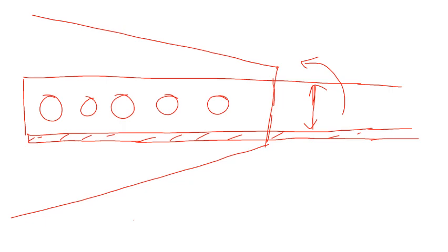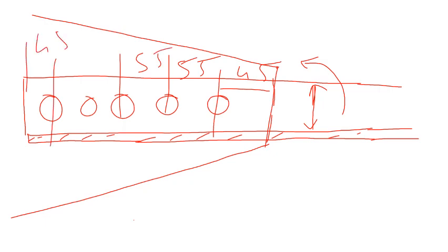So this edge distance we have calculated, this should be 45, and the pitch distance between these two should be 55. So this is again 55 and this will come again 45. One more thing we have to take, that is this particular angle and the angle on the back side.